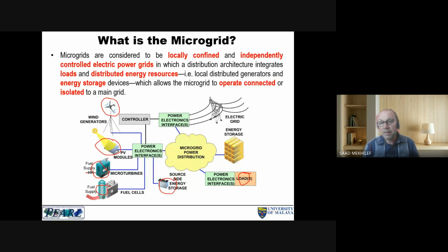You need to assess, because in renewable energy systems, one of the most important components is what you call site assessment, or resource assessment. For example, if I want to install a wind turbine, what do I have to do? I need to do site assessment or site selection. Assess what the wind speed is, what the direction of the wind is, and what the wind speed is with height, because as we know, as we go higher, the speed increases.